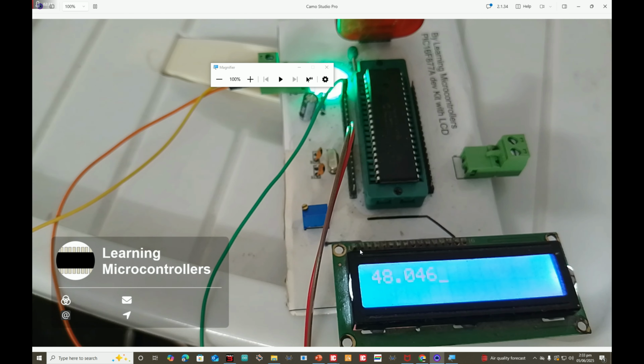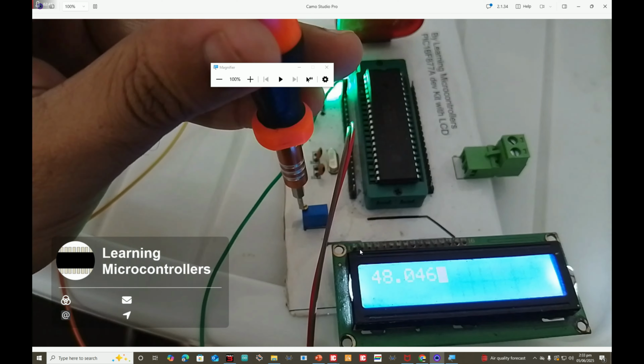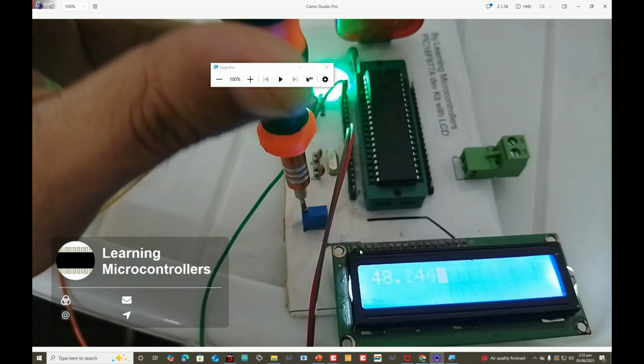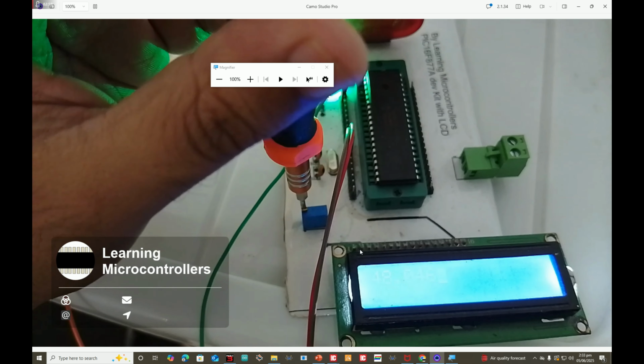Okay, the LCD is a bit blank. That is because the camera I am using is not of very good quality. Second problem is the LCD contrast. So we may adjust the contrast, because you have to adjust the contrast whenever you change the power source. So I just rotate this knob to set the contrast, whatever is preferred. Okay, now it is getting more dull.